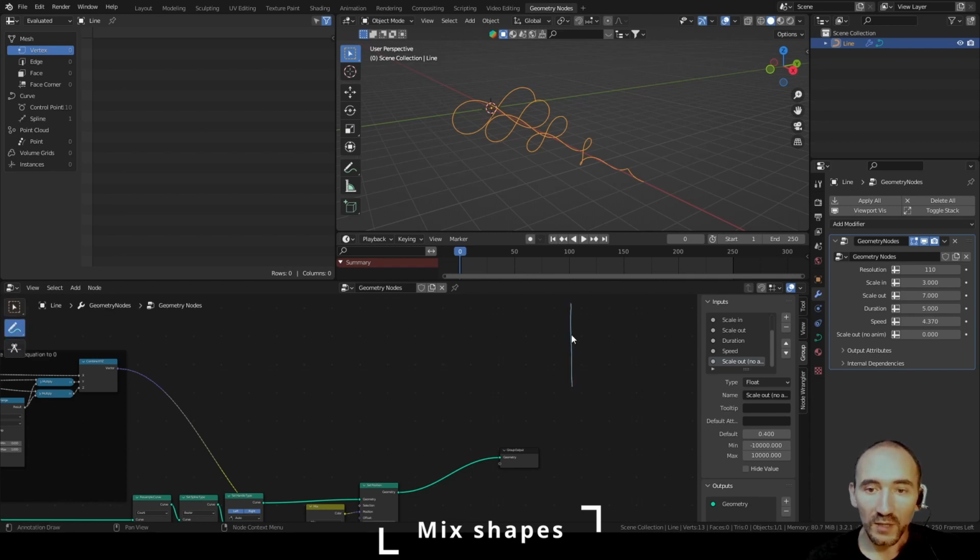One, we can use a formula called arctangent. So this is the formula. We can have this shape and we can shift it in the direction we want. So for us this will be the 0 vector and this will be the 1 vector. Or you can use a map range to have the same result but without having a long tail here. So you can multiply this equation with a high number to have this jump to mix the two shapes, and I will show you both of them.